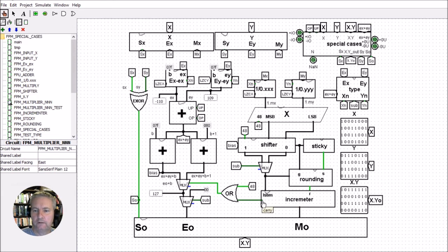In this instance, we can see that bit 48 goes high, so we're going to take that bit 48 and it's going to make that choice here, and the increment in this case hasn't rippled all the way up through to the exponent section. A thing that tends to get lost sometimes when people are building these is that they have this going through 2 possible incrementation phases.